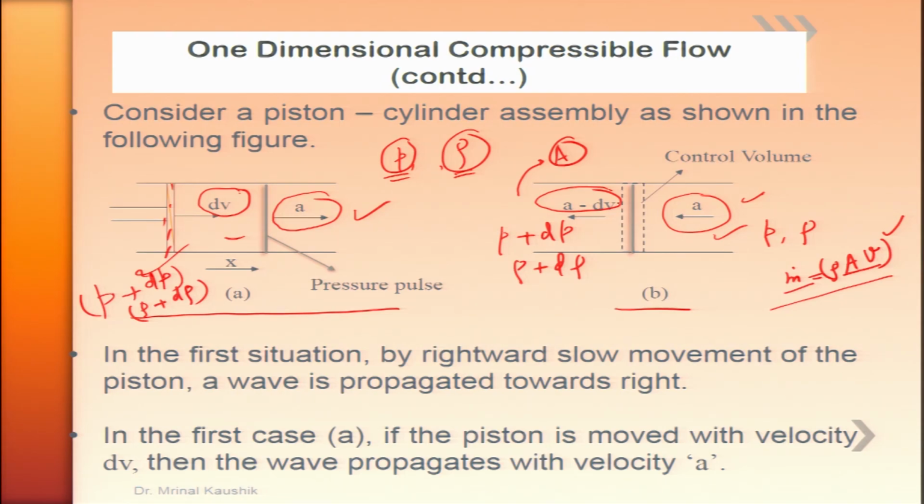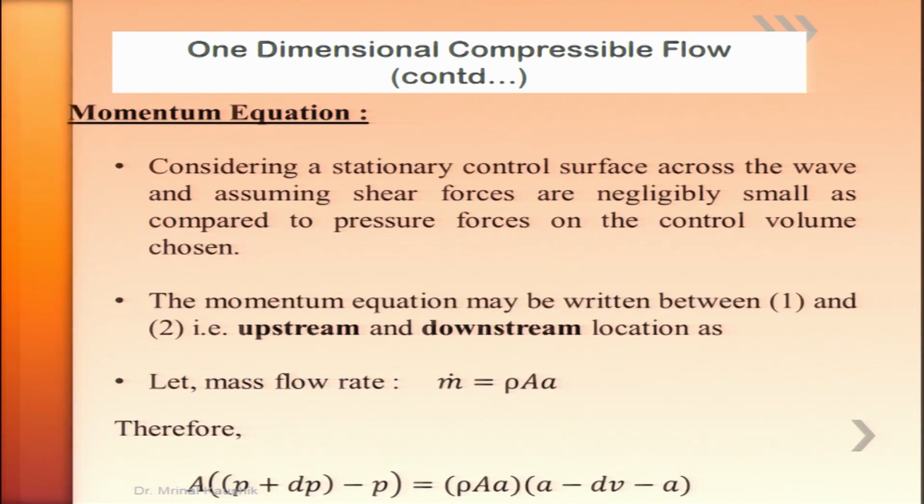Now, if we apply the conservation of momentum principle on this control volume, what information do we receive? From Newton's second law, we know that the change of linear momentum of the flow or any matter is equal to the applied force, that is F equal to ma. The same principle I am going to apply here.